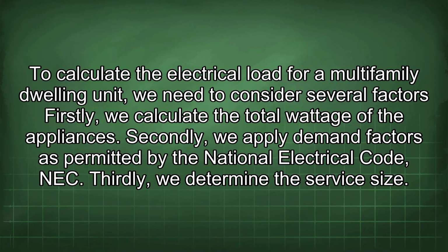To calculate the electrical load for a multifamily dwelling unit, we need to consider several factors. Firstly, we calculate the total wattage of the appliances. Secondly, we apply demand factors as permitted by the National Electrical Code, NEC. Thirdly, we determine the service size.